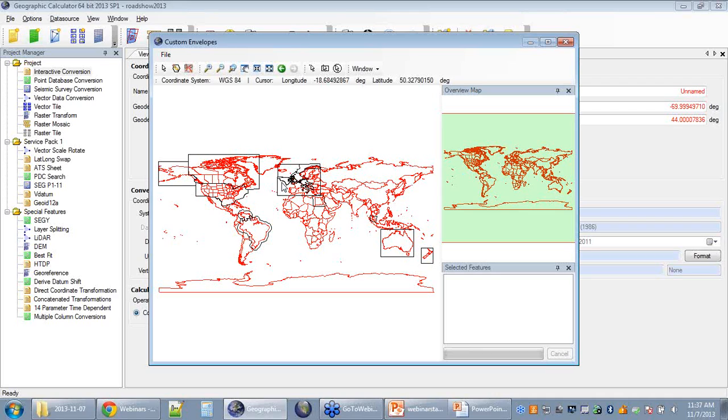What you need to save in those is simply polygons. The attributes don't matter at all. So all we need are some polygon outlines of a particular area. And to add those into the map, it's actually how we added in our basic out-of-the-box filters here. What we do is go up to the File menu, and you'll see there are some options there: Save, Close. This bottom option is Import Polygon Data.